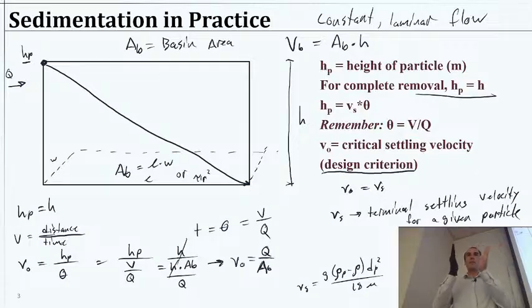If I give it a little pipe, a narrow channel, it makes its way through that pretty quickly. If it spreads out everywhere, it has more time to travel that distance, whatever flow rate I was giving it. So as you expand your area for sedimentation, your water slows down.